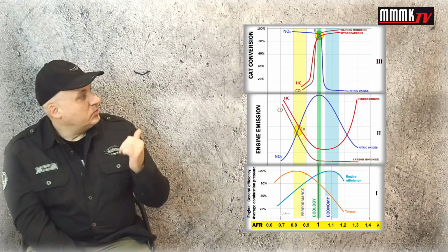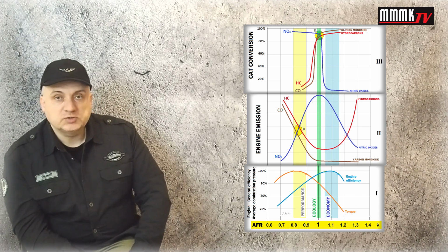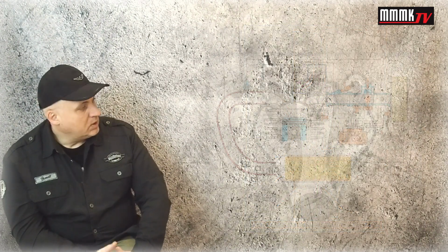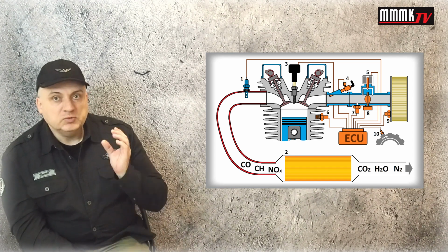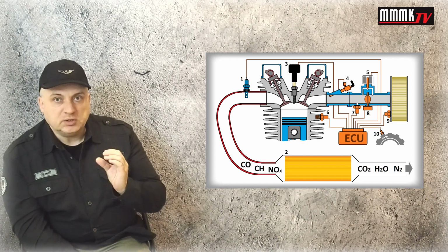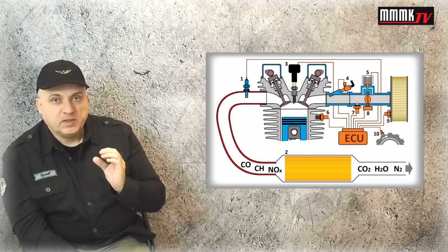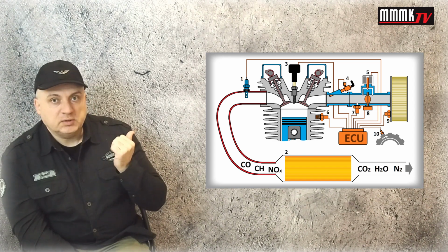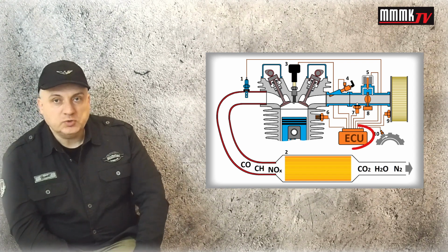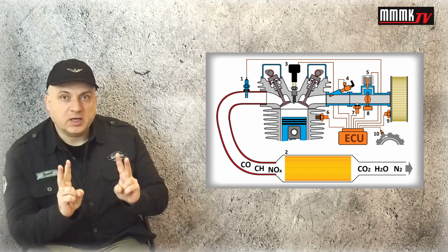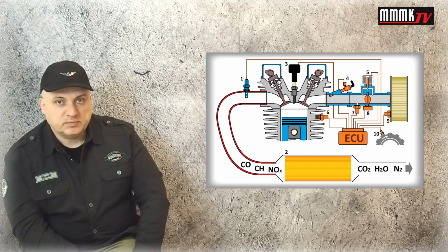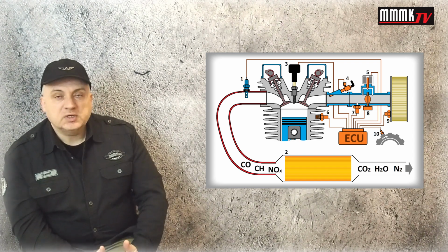So now we have to take a closer look at the fuel injection system, a modern one. A long story short, the injecting dose, the amount of fuel that needs to be injected into the inlet pipe, is being calculated by the ECU, electronic control unit. Well, as a matter of fact, it is not calculations as such, because the ECU doesn't calculate anything.